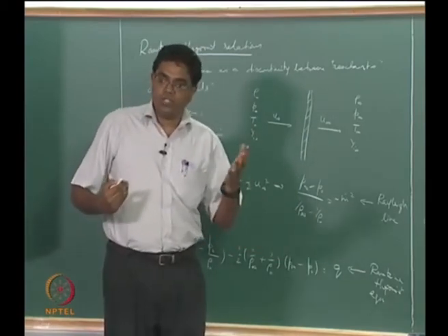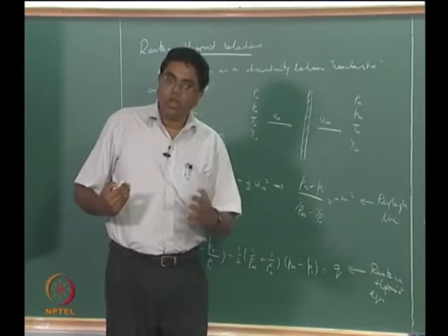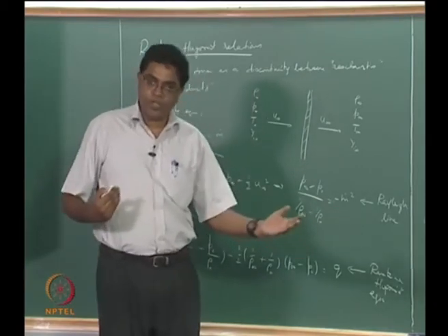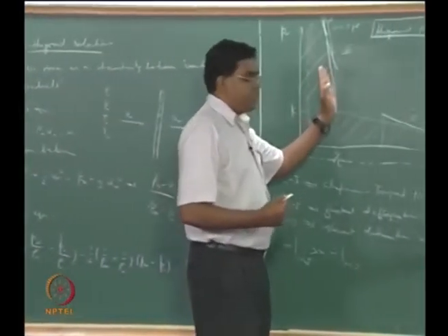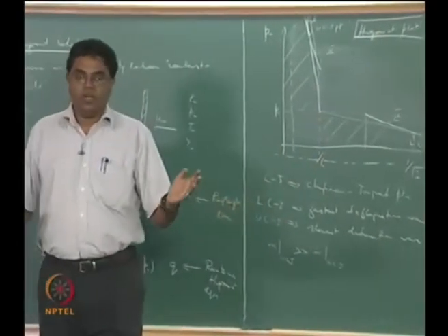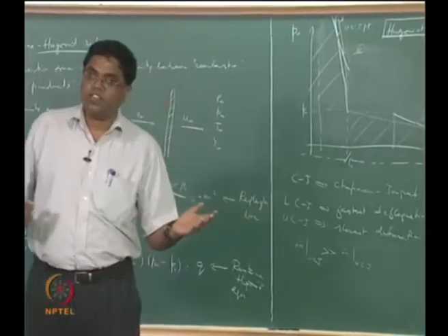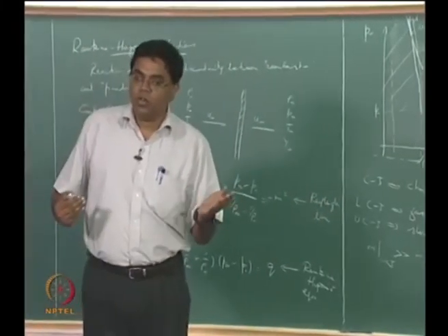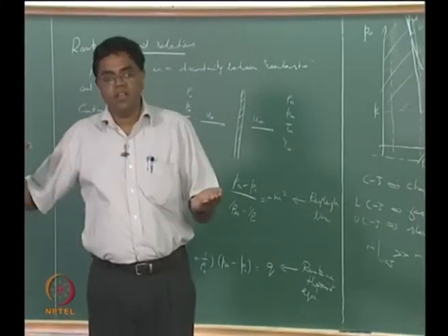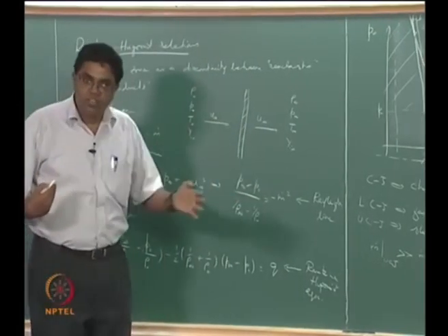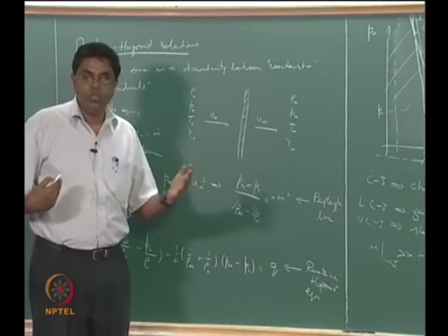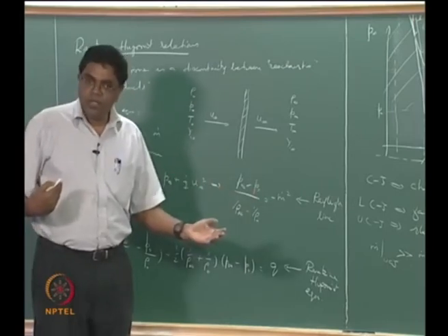So a lot of compression would mean a lot of deceleration all the way down to subsonic levels, whereas in a weak detonation you expect that the downstream product flow is still remaining supersonic, although not as supersonic as the upstream reactants. There is the deceleration alright, but not down to subsonic levels.